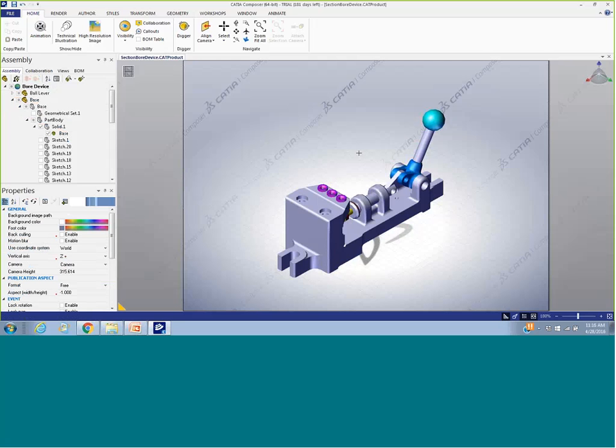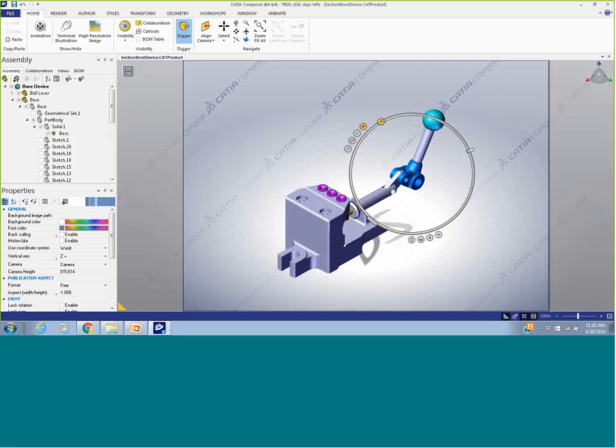Now you also have up above here what they call the digger. And so I'm going to go through and turn the digger on, and the digger is this ball, and I can move this digger around. And then once I get it in position here, what I'm going to do is I'm going to hit the button on the side here called the tool button. And when I do that, it shows me the tools are on the outside of this. Now, I'm currently in what they call onion skin mode. And so when I drag this one handle, it is going back and peeling the skin of the onion away. So it's going further back into the model.